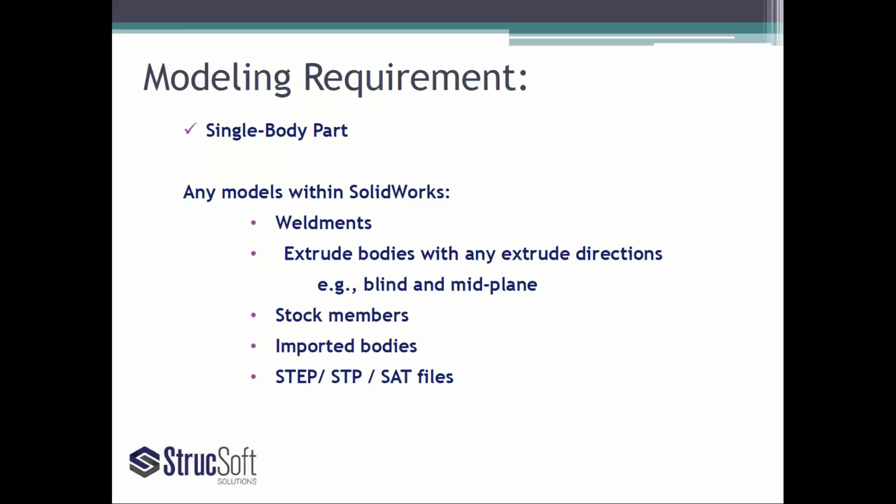Additionally, we do read your stock members, and if you open any part from a CAD platform and it comes in as imported bodies, we also read that. The same goes for your STEP files. You don't have to run any feature recognition tool to process your STEP files to use our current solution to produce your NC1 file. We're going to talk about those steps in our coming slides, and then we'll do some examples as well.